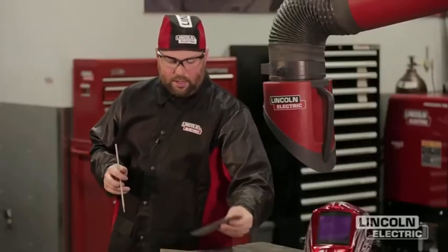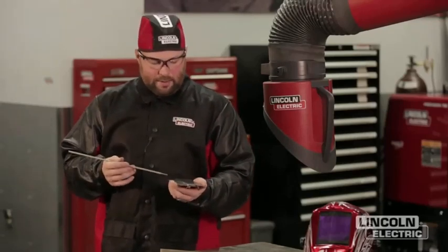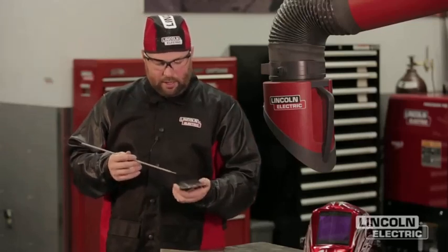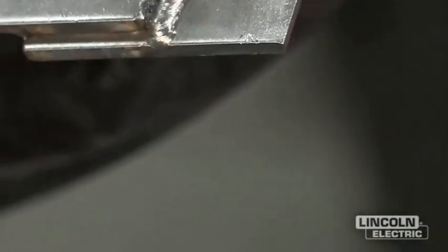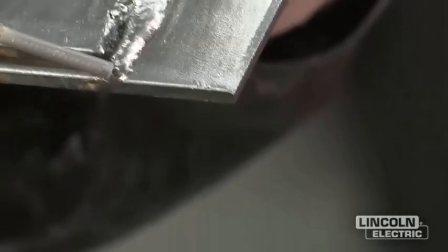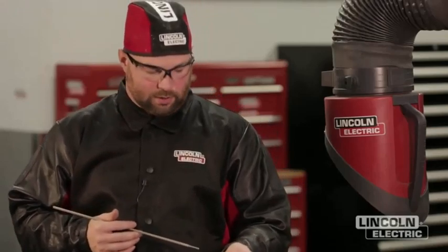The other criteria that we're going to look at is proper placement in the joint. Obviously we want the weld to be in the joint. We don't want to be straying out of the joint. I've got an example here of a lap joint, and we've got a fillet weld on here. If you look right at the beginning, it's actually more on the bottom plate than the top plate. That's what we're referring to as proper placement. You can see as we started the weld, we noticed we were on the bottom and then came back into the joint and proceeded down the weld. So again, making sure the weld is properly placed is also a key criteria to look for in your welds.